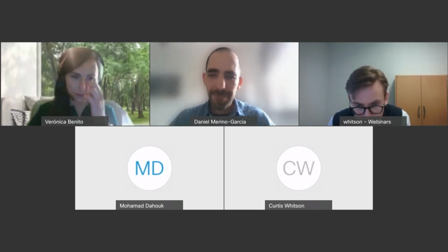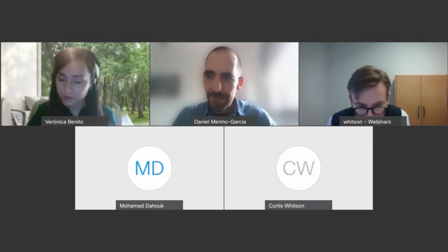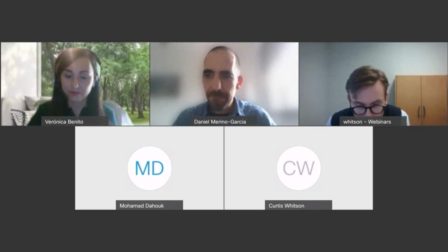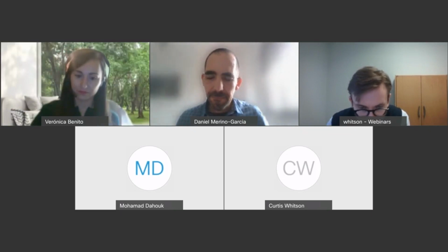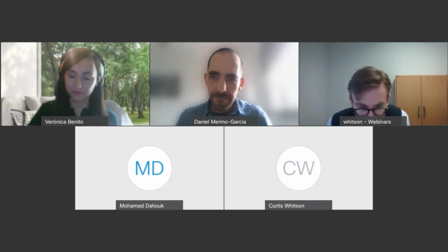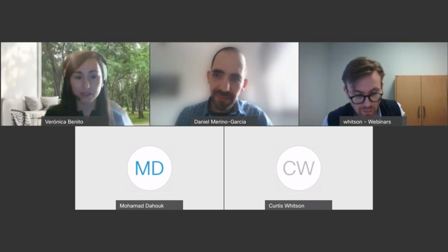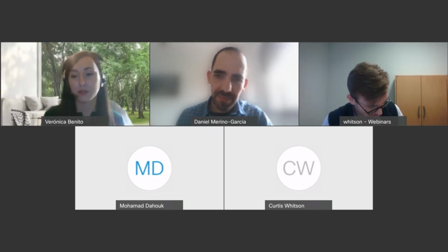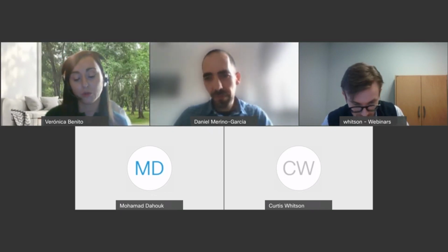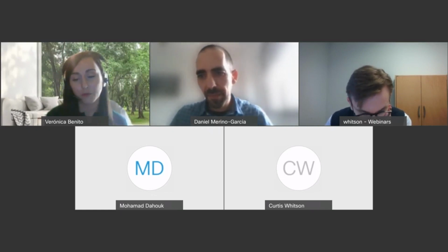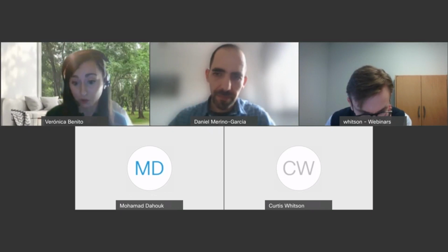Excellent. Then for Veronica, there's a question along the lines of what you're talking about, Danny. Is it really possible to use one unified equation of state model for the entire network, taking into account all the compositional changes you observe during the life of an active field? Yeah, it's possible. Sometimes it's not easy, but as Daniel has mentioned, it's possible. Our idea is to use an integrated fluid as much as possible in order to assure consistency between the different parts of the network.